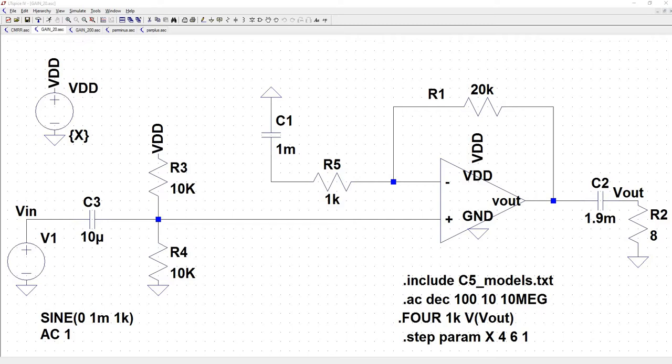Alright, so now we're getting into the fun stuff. This is the op-amp I designed as a MOSFET replacement to the BJT-based design of the LM386, which is an infamous audio amplifier. I wanted to go over the circuit just a little bit. So we've got a negative feedback configuration loop here. We've got the voltage applied to the V plus terminal, which means we've got non-inverting configuration.